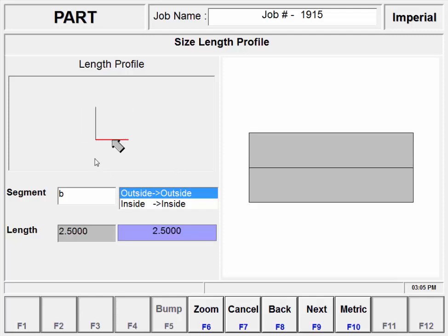Now I'm going to create the bend. I'm going to make a 2-inch radius on this piece. So the radius will fill in where these lines are now. You'll notice I made my lines 2.5 inches long. The reason I do this is if I want a 2-inch radius part, I do need some extra meat on either side of this, at least for the program, so that I don't get an error in my program. You'll see this as I continue. Okay, so I'm done dimensioning.